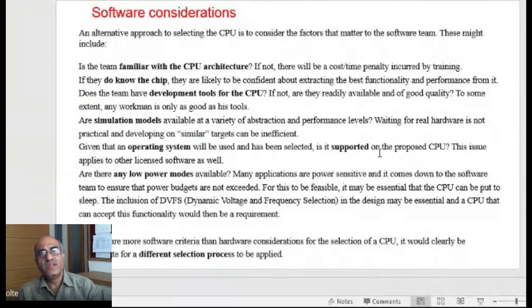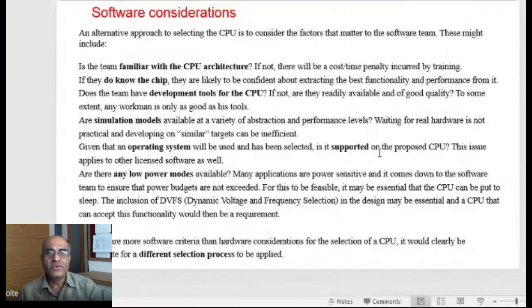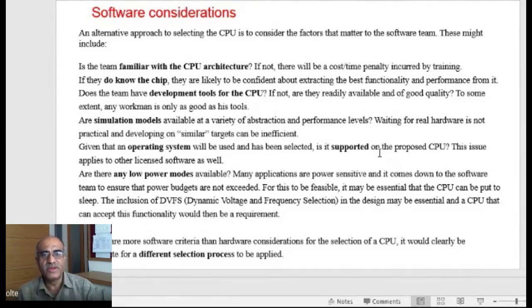Then the next part is low power modes. When we have a CPU along with the embedded system, or ARM, we have a variety of ARM processors. Out of those, we have to check which ARM processor has to be used for this embedded product. Is each and every algorithm needed there, or can you stop it or mute it, keeping the CPU in a sleep mode so that you can do some other function and the power consumption is reduced? So this is the power budget.